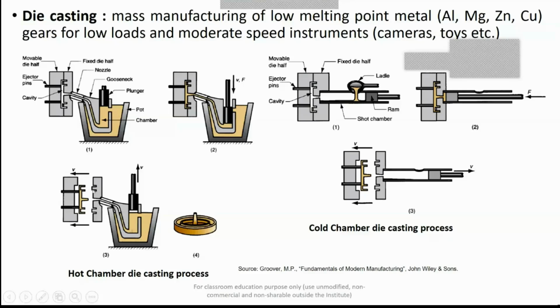And in the final stage, the die opens up, and with the help of these ejector pins, you have two ejector pins to eject out the solidified component, and simultaneously this plunger moves upward, and then it also gives a pathway to enter your molten metal into the chamber.